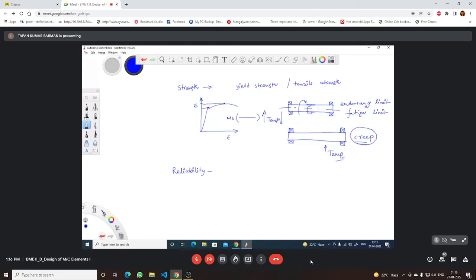And if the reliability of the product is say 50%, so there is a chance that 50% of the product fail within the specified limit, then the manufacturer has to pay a damage to those products, and that is the liability of the company also. So in the company, they try to optimize the things, and suitably, they want to make the reliability of the product so that it is reliable. At the same time, the cost of the product can be minimized or optimized in a better way. So reliability is also another design aspect or fundamental design consideration that should be used at the design stage.